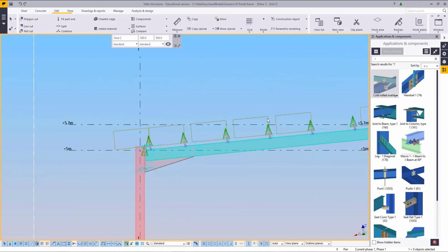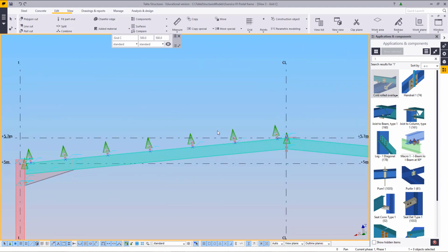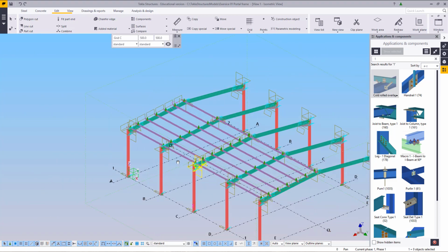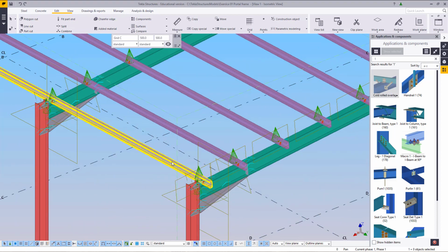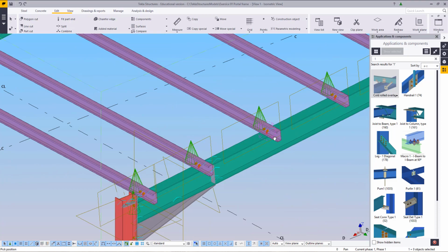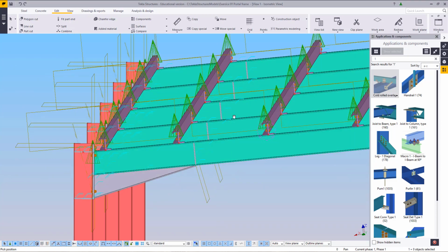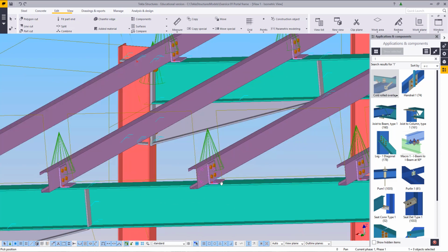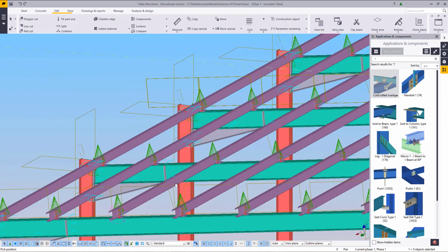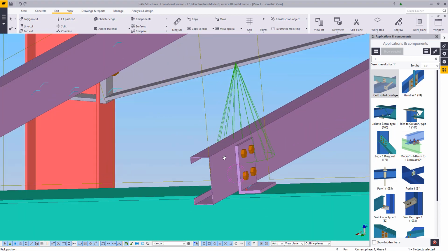Now we've got our entire row of purlins. The next thing I want to do is rectify a small mistake that I made doing this. Usually you want your purlins facing upwards, so that when they do the installation they can simply lean the purlin up against the cleat and from there bolt it one at a time, instead of holding it there while they're doing the installation.